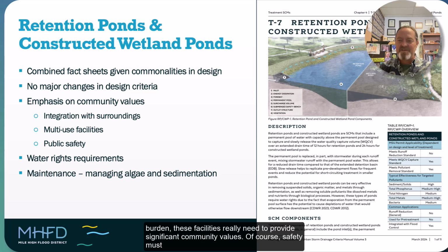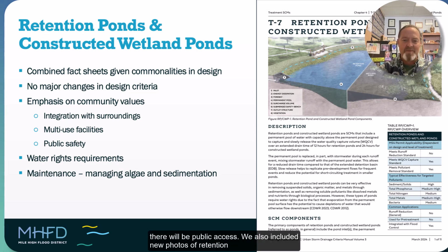Of course, safety must always be a consideration when designing a facility that will have ponded water, and the fact sheet provides guidance on safety measures, including edge treatments to discourage access and safety benches in areas where there will be public access.